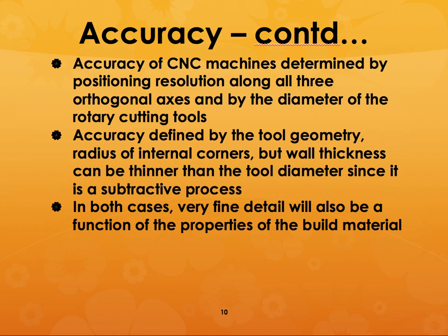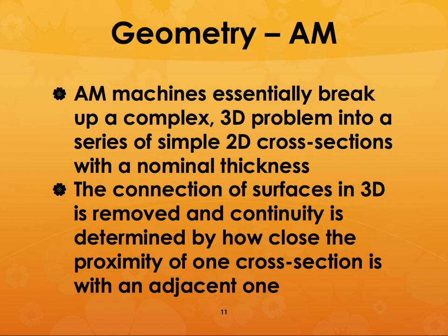But what is also important to note is that it is also a function of the build material and the support material. Essentially, what are you doing? You are breaking up a 3D problem into a series of 2D cross sections with a nominal thickness.